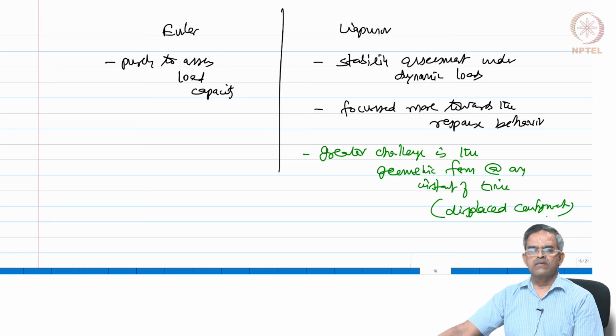In case of structures which are form dominantly designed like TLPs, they are permitted to undergo large displacements. So, one should ensure that under such large displaced condition, the geometric design ensures proper recentering, and therefore, the load carrying capacity is not close to 0. Okay? That is a very important condition.